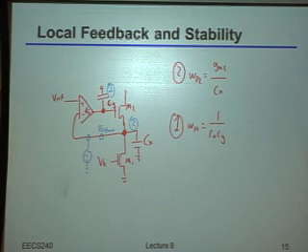Yeah, exactly. So if you look at the ratio of those poles to 0 order, then you should basically place them far enough apart that they're spanning the gain of the amplifier in the first place. Okay? Now, I didn't give you any exact mathematical condition as to what exactly the phase margin of that is, but it turns out that's actually very easy to work out. And I won't do it for you. I'll actually give that to you in a homework. Okay? But indeed, to 0 order, you always have to space them roughly the gain apart from each other.